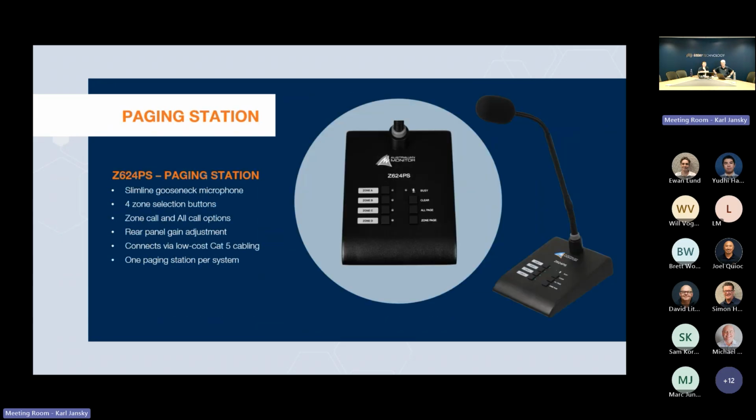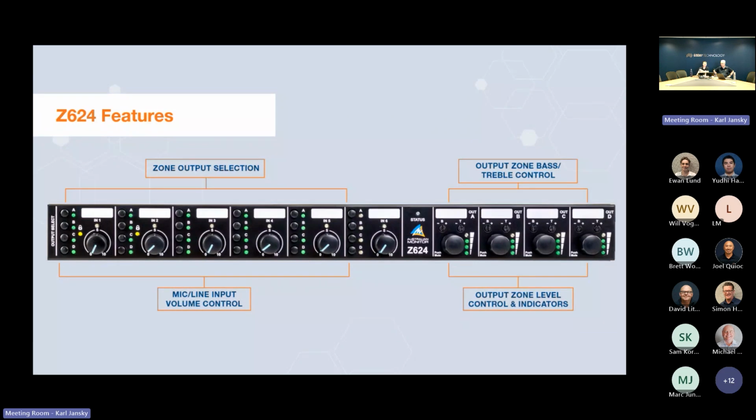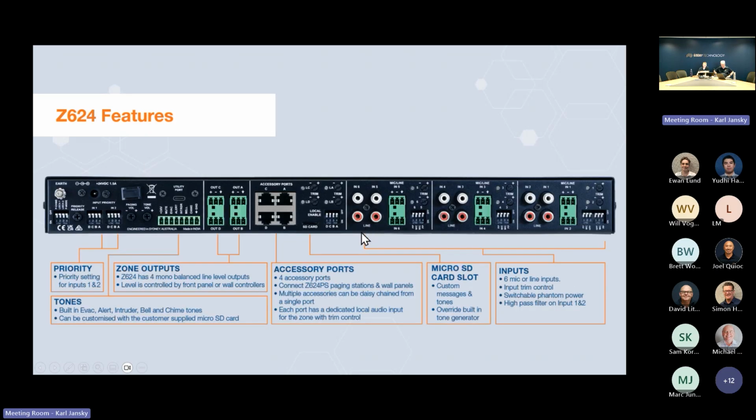You would then press this dip switch down, and what it does is it replaces input 6 on the front panel of the product. So I'm going to jump back to the front panel, and you'll note that on input 6, it has slightly different colored LEDs, that they're not green. So on input 1 to 5, they are standard inputs, but on input 6, if you choose to use a local input, it will replace the rear panel input 6. So if you had on input 6, say a CD player, for example, that would be shared on all output zones.